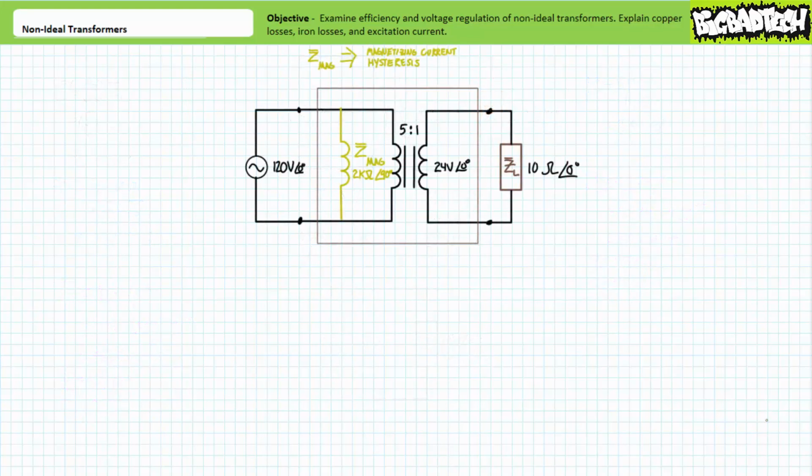In the previous analysis, we assumed the source supplying the current to an ideal transformer saw only the reflected impedance equal to the load impedance times the turns ratio squared. Given magnetism is essential to the operation of a transformer, it stands to conjecture that the source might see something more than the reflected impedance, principally the reactive portions of the windings comprising the transformer. Various models account for the reactance of transformer windings.